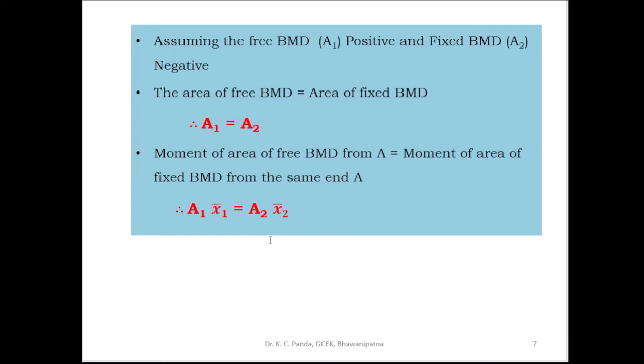So these are the procedures. You have to apply them to find out the fixed end moments. Then you can draw the bending moment diagram and shear force diagram. Then you can find out the point of contraflexion. Then you can also find out the maximum bending moment position.